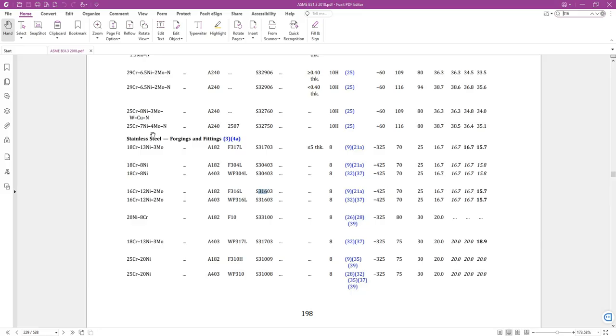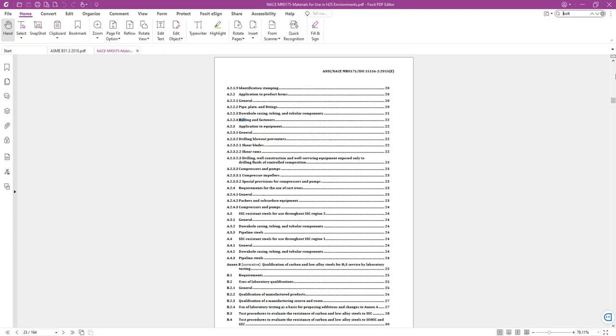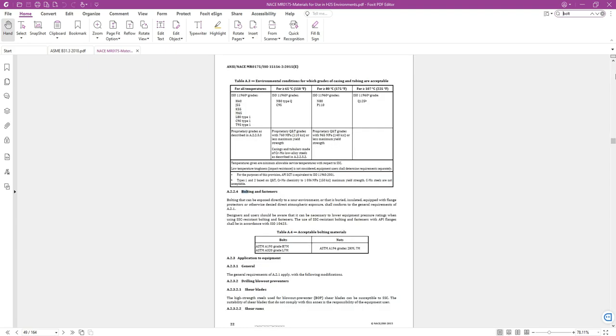The next step is specifying of nuts and bolts materials. For this purpose, we have two important factors we need to consider in our material selection. The first one is our process gas is sour. The bolt and nut material must be ASME B31.3 qualified. Then it must tolerate our low temperature conditions. Let's open ASME B31.3 standard to see the pre-qualified nuts and bolts grades.